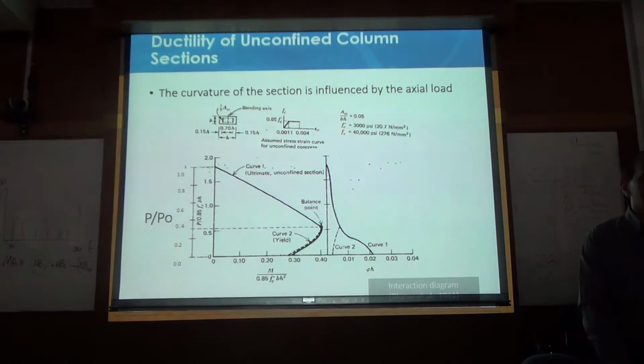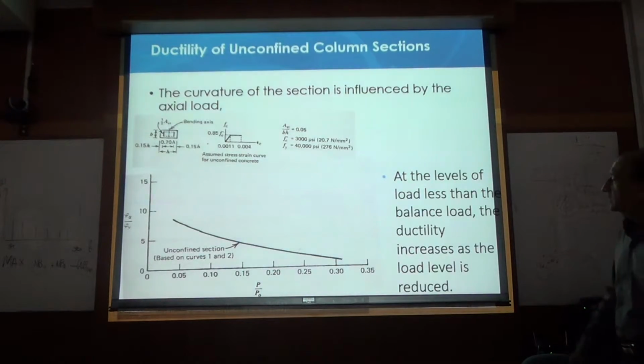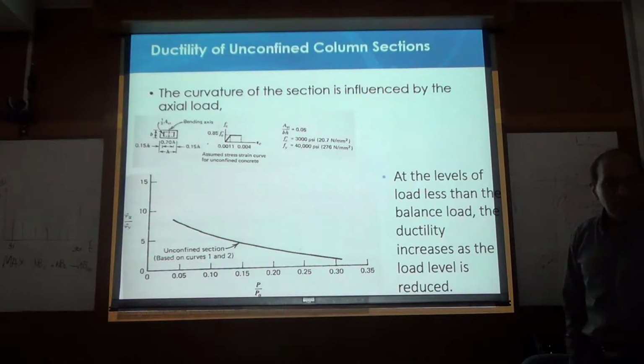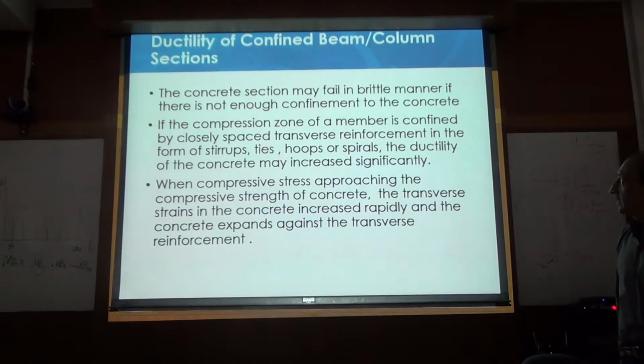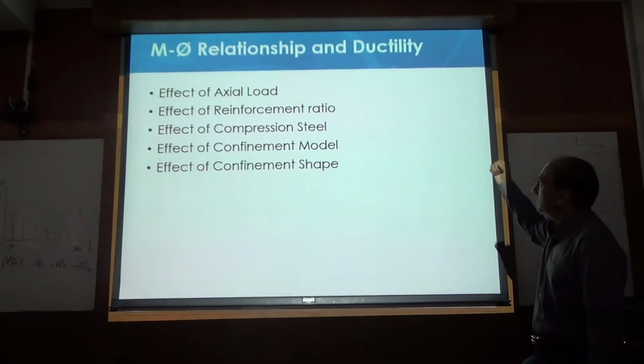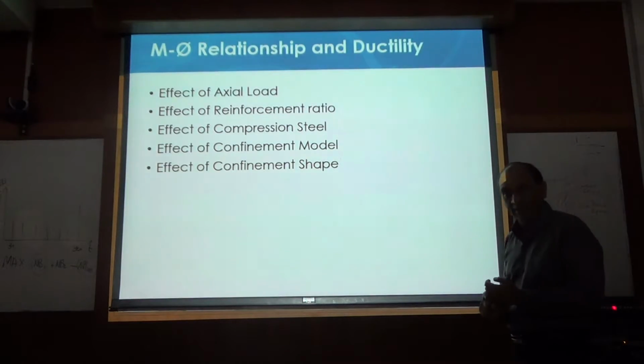Always look for a solution that is to solve the problem at the source. Do not let the problem come and then solve it. And this is the effect of the axial load, we already have seen it. If you increase the axial load, the ductility will reduce. So we know that. Confined, now same thing. So the moment relationship and ductility are related, as you know very well. Effect of axial load, we have to study that. We can play with that. Effect of reinforcement ratio, we can play with that.